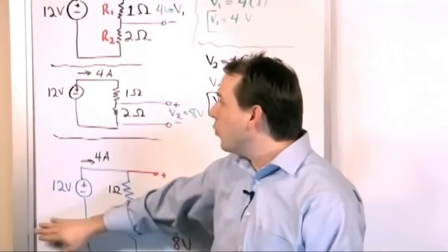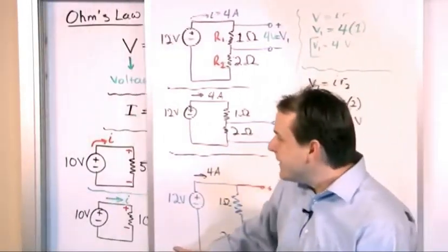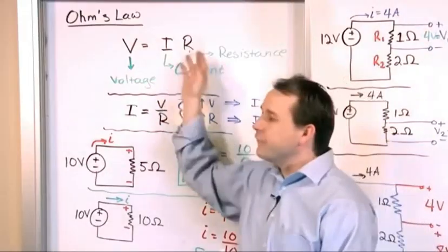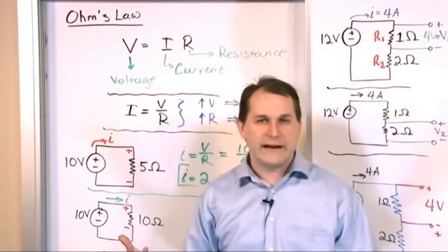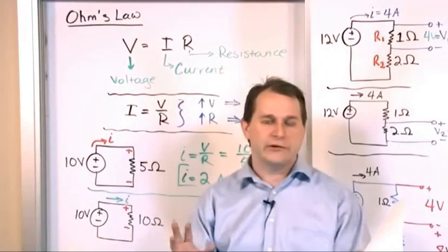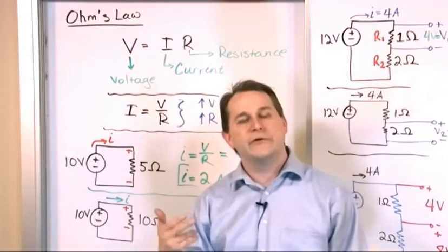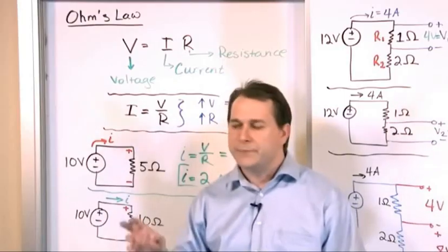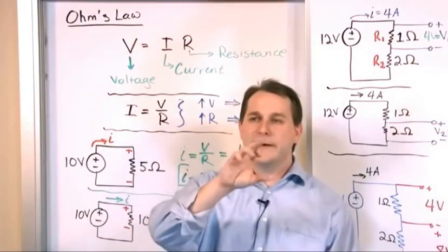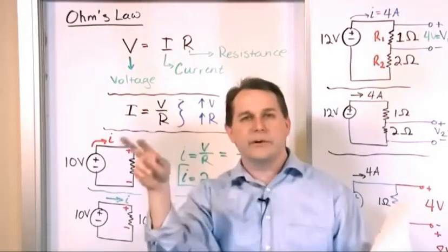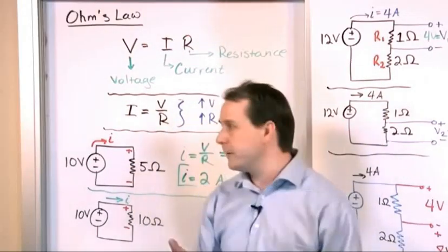It's one topic and one topic only, and it's so important that it deserves its own section. We call it Ohm's Law. Basically, it governs what we've talked about in words, that if you have the push, which is the voltage, and your resistance, which is in the way, so to speak, then if you know those 2 values, you can calculate the current flowing in a circuit. Ohm's Law applies to the whole circuit, but it also applies to the individual elements that the electricity is flowing through in a circuit.